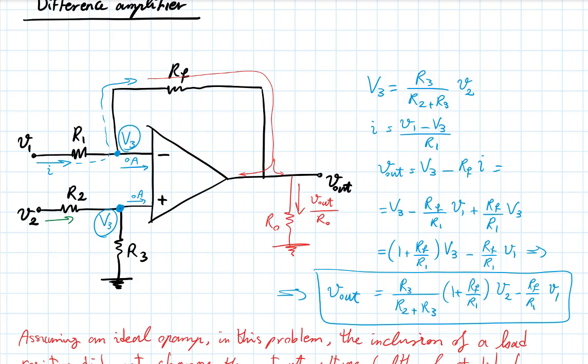You have a circuit here that, let's say, you give 1.5 volts at the input V1, and let's say it requires 1 amp to function, if this current I in blue is 1 amp. Well, it means that whatever is connected here will have to provide that. And if it can't, then these equations break down, right? So indeed, you will not get the output that you're expecting, and something somewhere will go wrong.